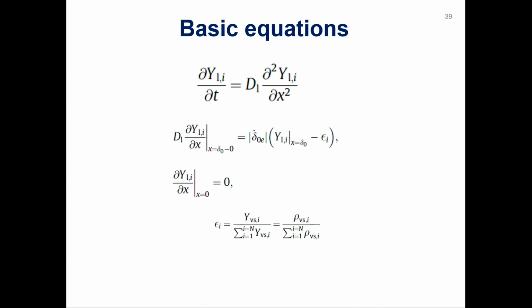And in a very similar way, we considered the species diffusion inside the film. So the film is multi-component. And this assumption is absolutely essential for the application to automotive engines, because all automotive fuels are multi-component. There is no such thing as a monocomponent automotive fuel.